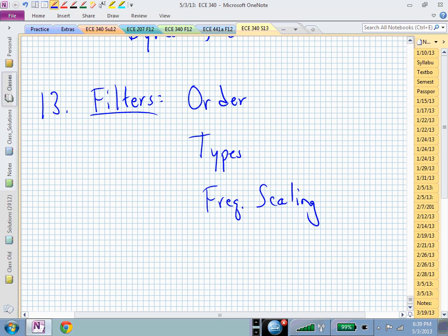And the Butterworth design is the one that we're going to focus on, in terms of what's so special about the Butterworth. It gives us our pole pattern, doesn't it? And that pole pattern is nice because it's neat in the S-plane. It's symmetric with respect to the origin. Everything is nice that way, but it also gives you a maximally flat pass band. Questions? Hopefully it's clear what's there.